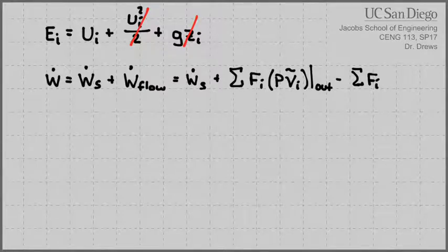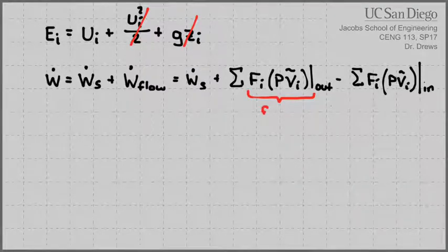So each of these terms, the flow work, looks like a PV term times a molar flow rate. Why did we switch ins and outs? That's just the convention that we chose for work. You could switch all these conventions and make the signs different. You have to end up with the same answer. So these are the flow work terms. They represent the amount of energy required just to move that element of fluid from point A to point B by means of a pressure gradient.